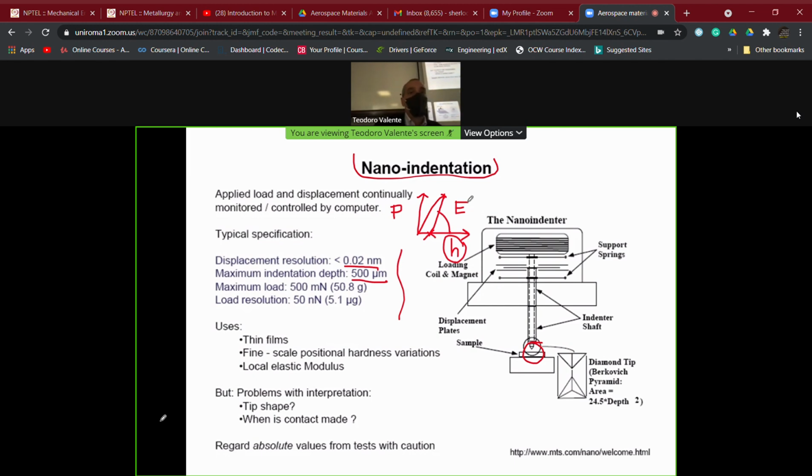And thus we can have three of the most important parameters which are able to characterize the mechanical properties of the surface itself. You see here, we cannot use any CT specimens like in bulk materials to have a measurement of the fracture toughness. We are not going to use a standard tensile test in order to have an idea of the Young modulus or of the yielding strength of the materials itself, because these testings, the ones I have mentioned, are suitable for bulk and they are not suitable for surfaces.